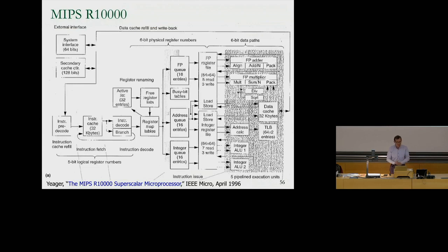So it's another machine, MIPS. Did Frank tell you what the MIPS acronym stands for? MIPS? Anybody? It's not millions of instructions per second. That's a different acronym. MIPS initially was a design that came out of the philosophy that hardware should be extremely simple. This is the philosophy of reduced instruction set computers, or simple computers. They basically said, we're going to make hardware extremely simple. All of the code scheduling will be handled by the compiler.